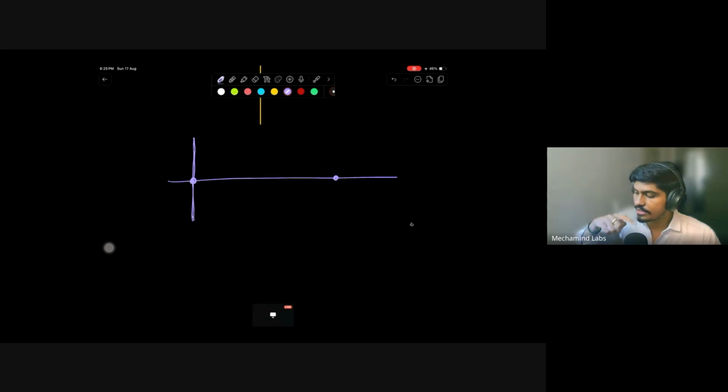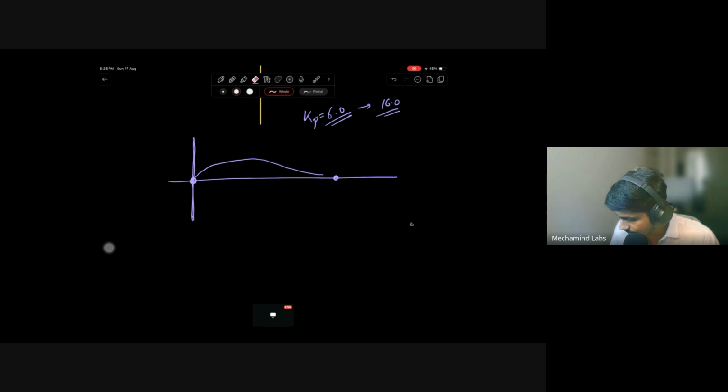So what happens is that if I put the angular value very high, and I want to go from this position to this position, and the angular constant is very high. Right now I'm using kp angular as 6.0. Say for example it is 16.0, it is very high. So this turtle, instead of moving and going here like this, will start wobbling and going here like this, because it turned at a very high rate.